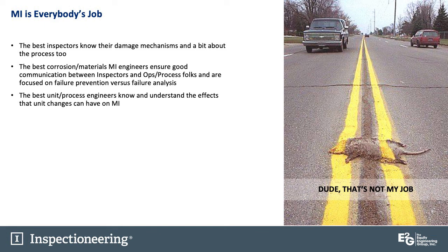The best corrosion materials engineers ensure good communication between inspectors and operations process folks. I've found they are the best go-between between the inspectors and ops process folks. And the best corrosion materials engineers are focused on failure prevention versus failure analysis. I always hate to go into a refinery and see that the corrosion materials engineers are spending most of their time on failure analysis. I'd much rather have them looking at IOWs, talking to process engineers, and talking to inspectors about maybe alternate inspection plans, and going back to process and seeing what we can do about adjusting some of these process variables that are promoting corrosion. That's proactive prevention of damage.